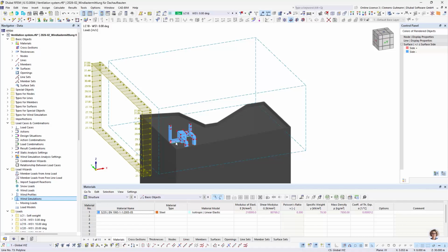But if there are intersections or anything's not CFD calculation ready, the shrink wrapping is applied. So now we have this volumetric mesh generator, and it now tries to snap to this shrink wrapping. We are going to look at later how that looks.